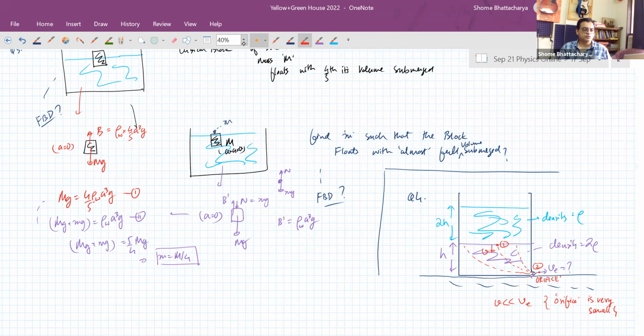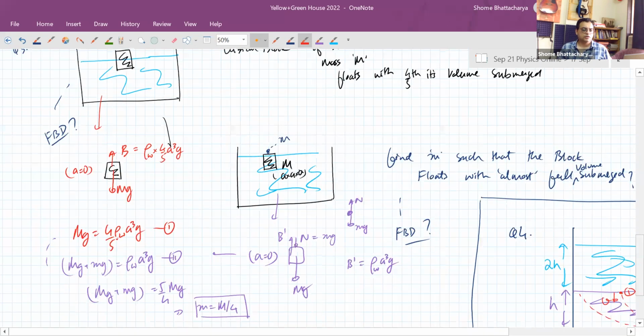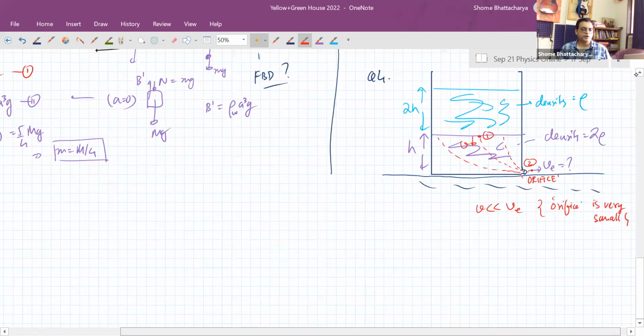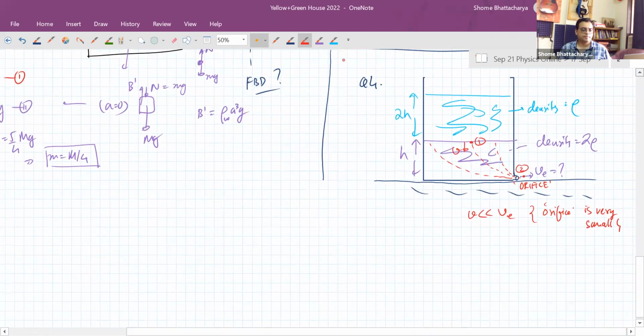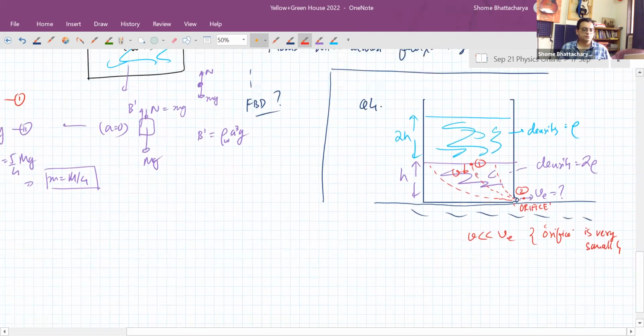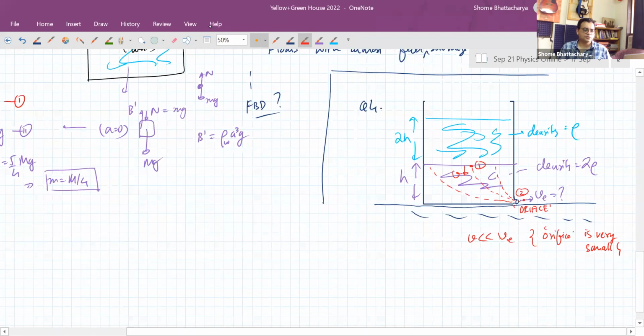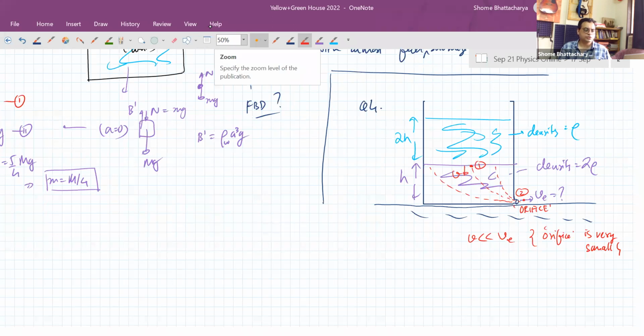So hope you understood the method I'm referring to, Tantresh. Try it out by this. Apply Bernoulli's equation between these 2 points, 1 and 2. The only adjustment you have to do is that point 1 is not an open surface now. So the pressure at that point will not be atmospheric pressure. You have to adjust the pressure properly.